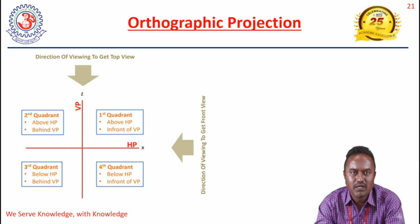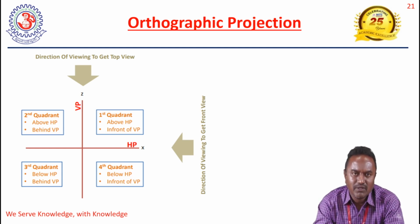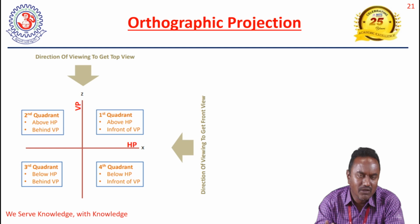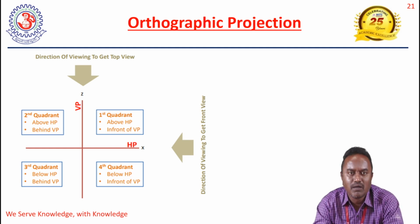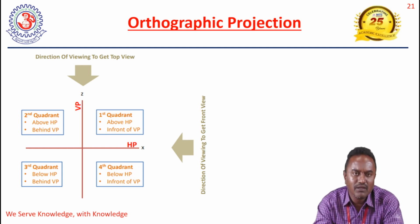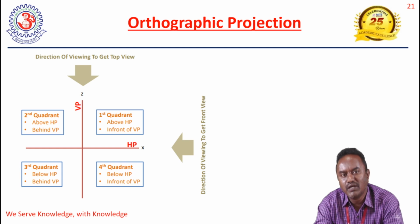The first quadrant is above HP and in front of the VP. When a point or line, whatever it is, any object is placed in the first quadrant, we can describe the point as above HP and in front of VP. In the same way, when we come to the second quadrant, the same point, line or any object is placed in the second quadrant, above HP, then behind VP. The same way, third quadrant is below HP, behind VP. Fourth quadrant is below HP, in front of VP.